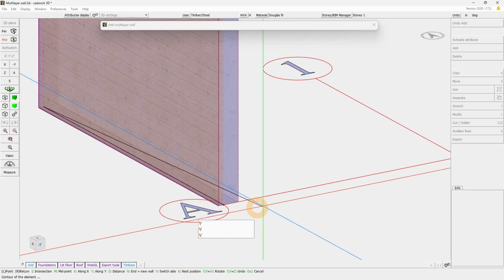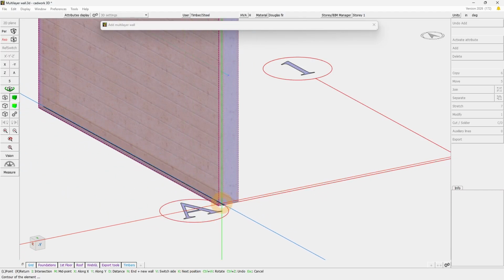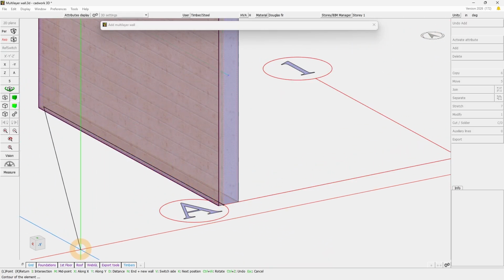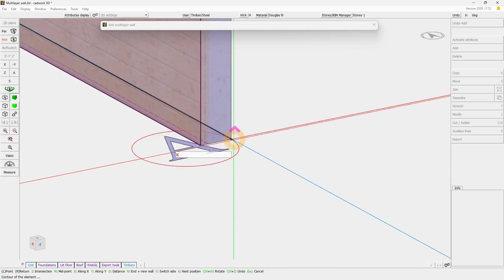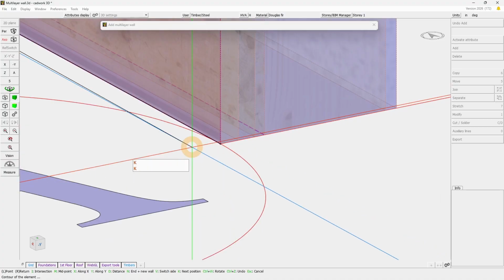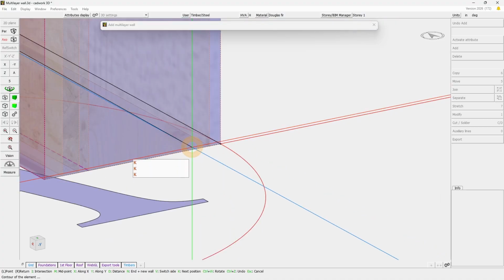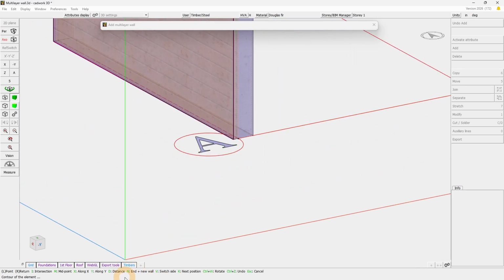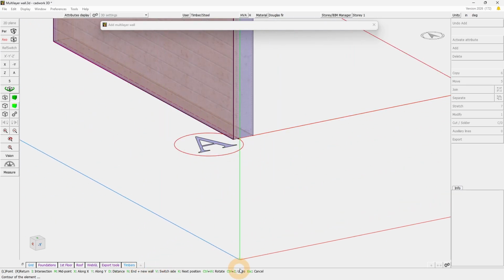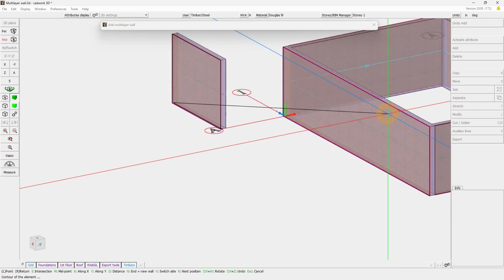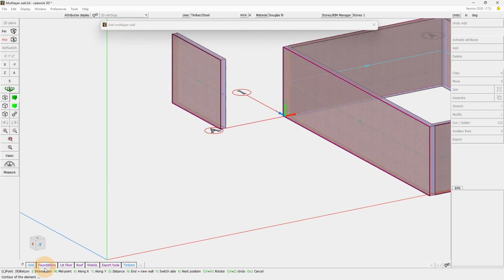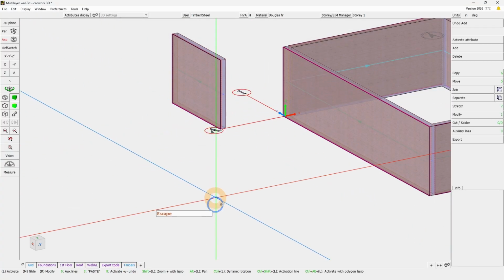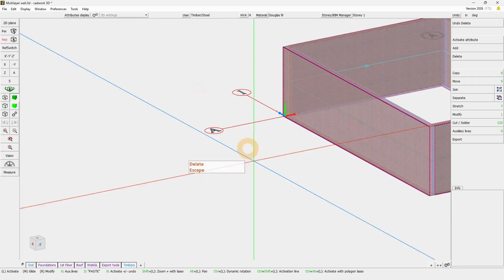You have then K, next position, that allows you to place the wall either based on the reference axis, as it is by default, or from the inside of the wall, or the outside of the wall. Pressing multiple times will simply glide your wall on. Of course, this is a change that you can do on every single wall you add in the model. So like this, you don't have to always start new when adding new walls that should not be placed exactly as the previous ones.